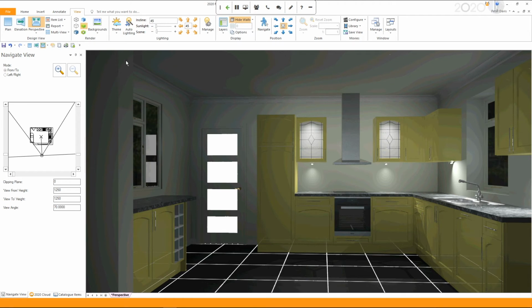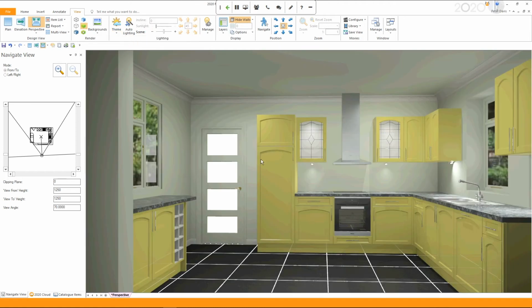Now I'm just going to make one small adjustment to show you an effect. So I'm going to again give you no outside lighting coming through, and I'm now going to press the plus tab. So here it is. Now the interesting thing is that what this will do is give you an exact copy of the original perspective. However, if I right click, I can actually say to it, don't take the lighting on the first tab, and you'll notice the color of the tab has actually changed slightly.